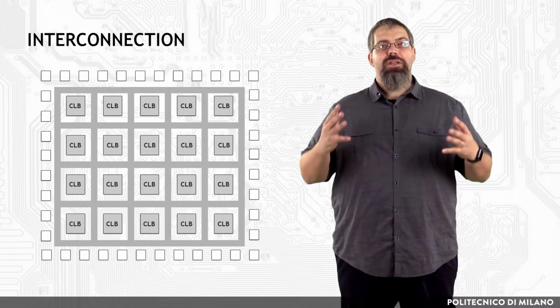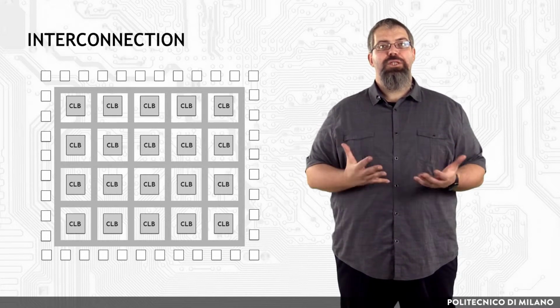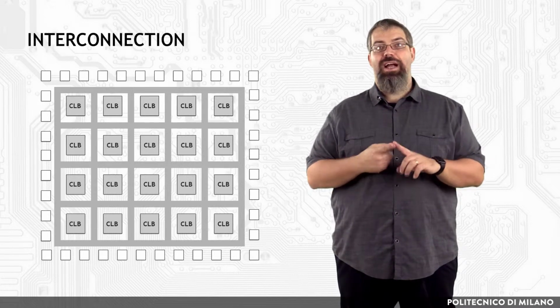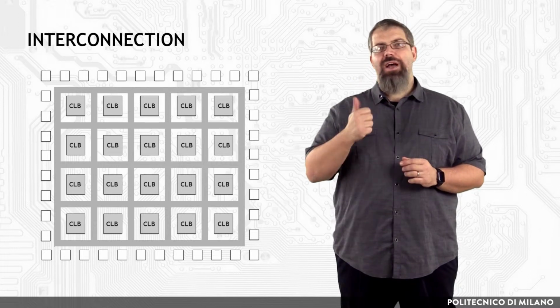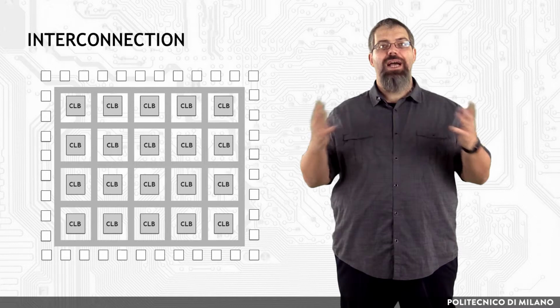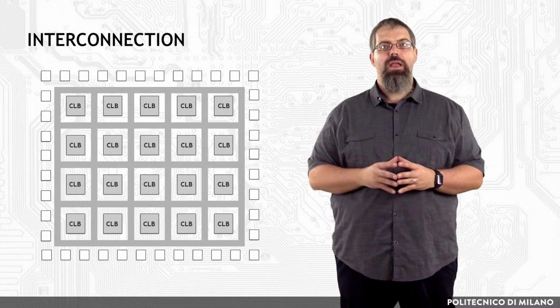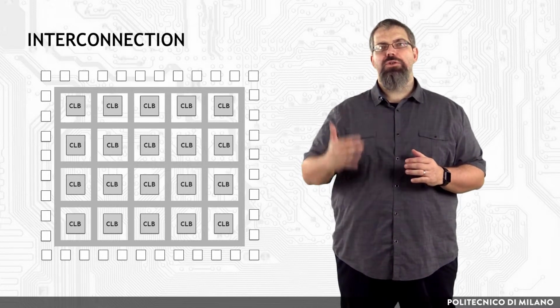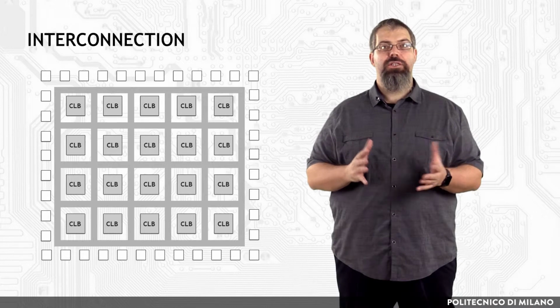Finally, the interconnection resources within an FPGA allow the arbitrary connection of CLBs and IOBs. The main modes of interconnection are direct and segmented. Direct interconnection is made of groups of connections that cross the device in all its dimensions. Logic blocks put data on the most suitable channel according to data destination. This implementation usually includes some additional short-range connections that link nearby blocks.